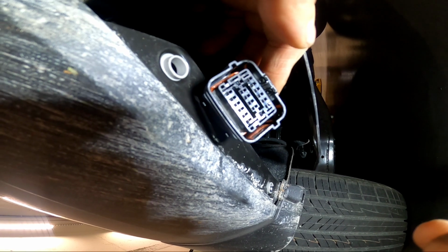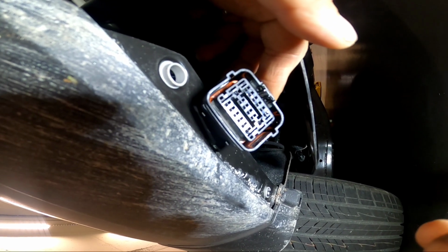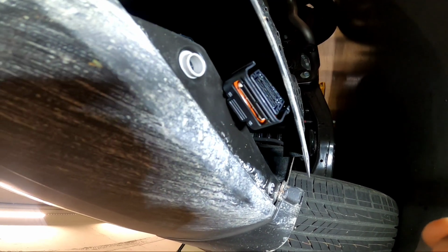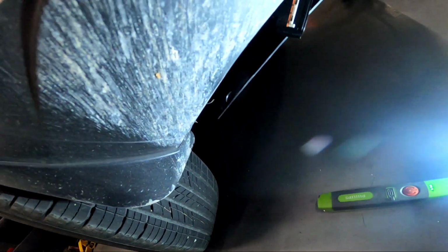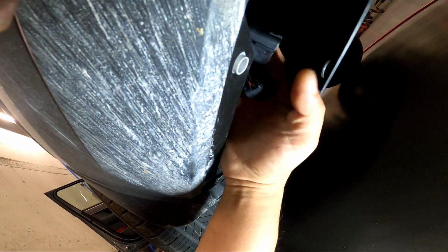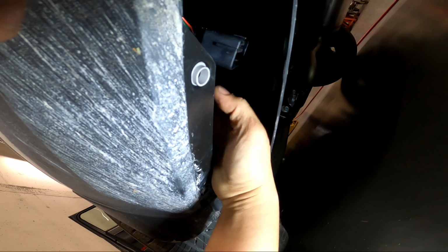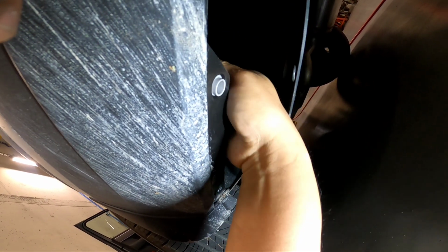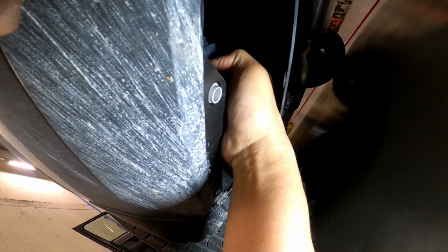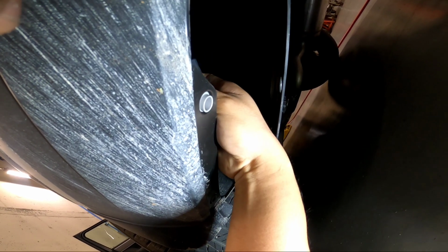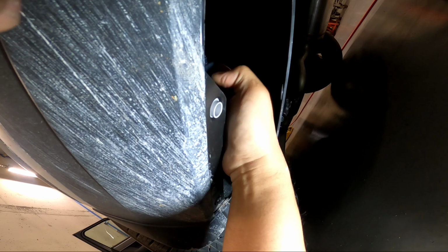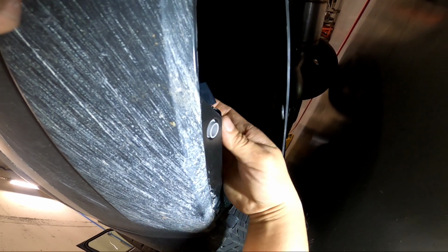So I'm going to dry that off and plug everything back in, and then let's see our waveform and check our codes. Okay, so I just blew some air in our connector. I'm going to plug this in now. Later, if blowing the air fixes the issue, I'm just going to cover this connector, because there's already a cover on this side of the vehicle.